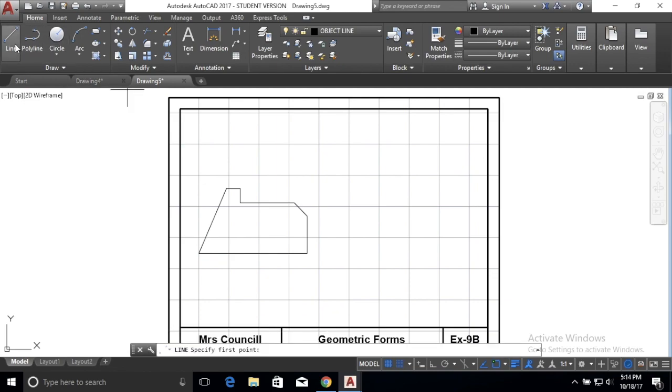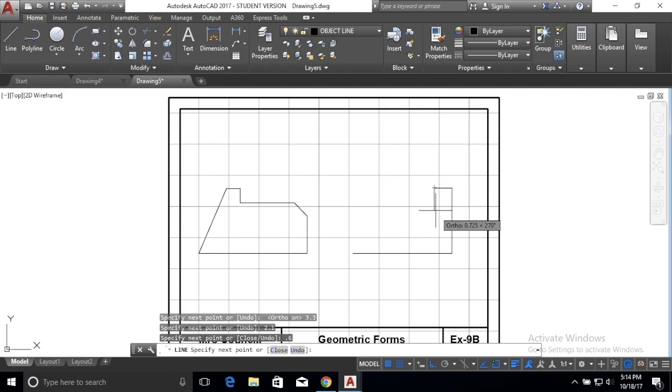This next one's going to be a little bit easier because there are no diagonals. So I'm going to start at this first point, go 3.3 inches to the right, 2.1 inches up, 0.6 inches to the left, 0.6 inches down, 1.2 inches to the left, 0.9 inches down, 0.6 inches to the left, 0.3 inches up, 0.9 inches to the left, and then 0.9 inches down to the beginning starting point. And now you are done. You can save this and export it.